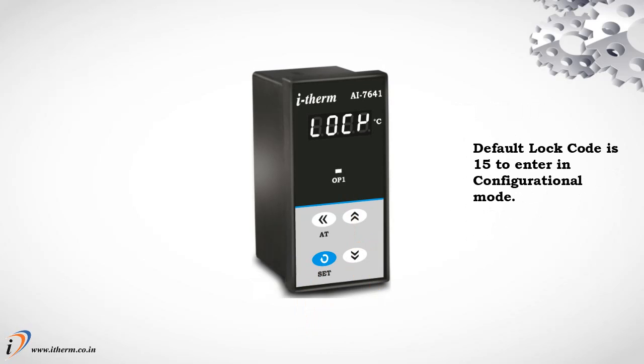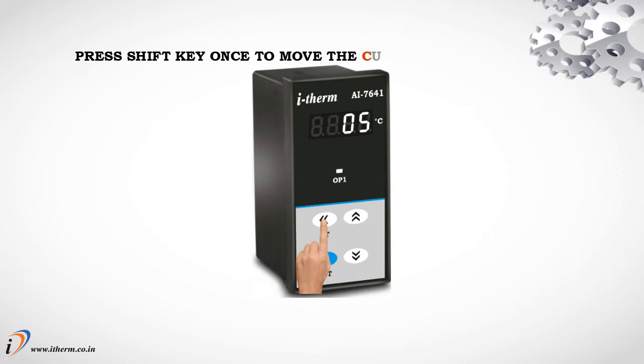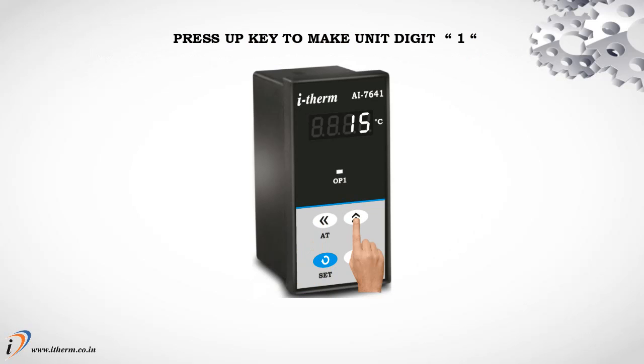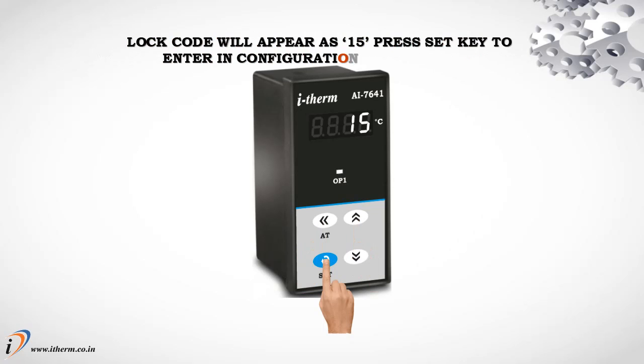To enter configurational mode, press the up key to make the unit digit 5. Press the shift key once to move the cursor to the next digit. Press the up key to make the unit digit 1. The lock code will appear as 15. Press the set key to enter the configurational parameters.